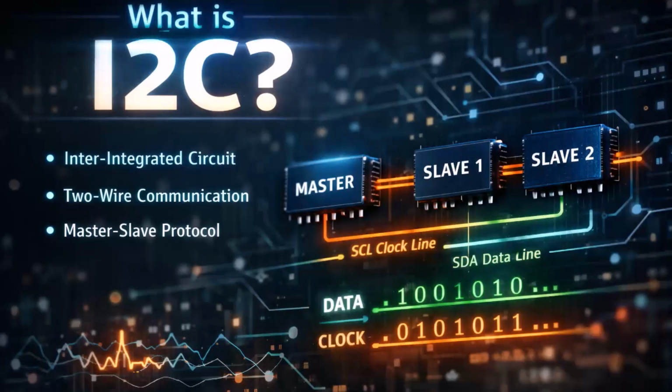I2C is a communication protocol used to connect devices like sensors and displays. Instead of using many wires, it only uses 2 lines, SDA to send data, and SCL for clock. This makes it very efficient and widely used in embedded systems. So instead of connecting 6 to 10 pins like a traditional LCD, we only need 4 wires.